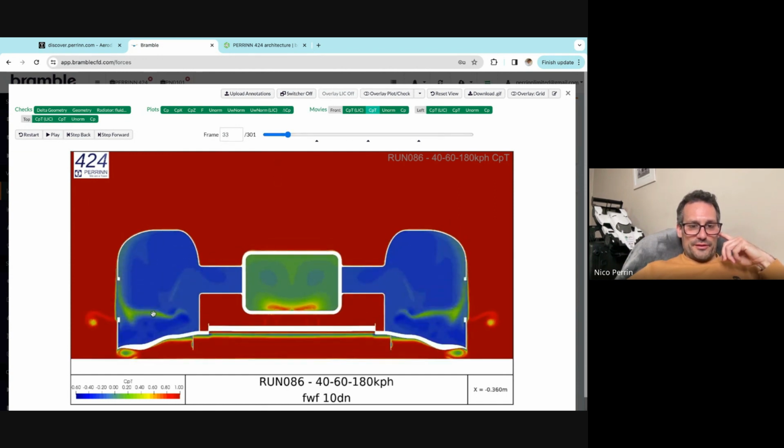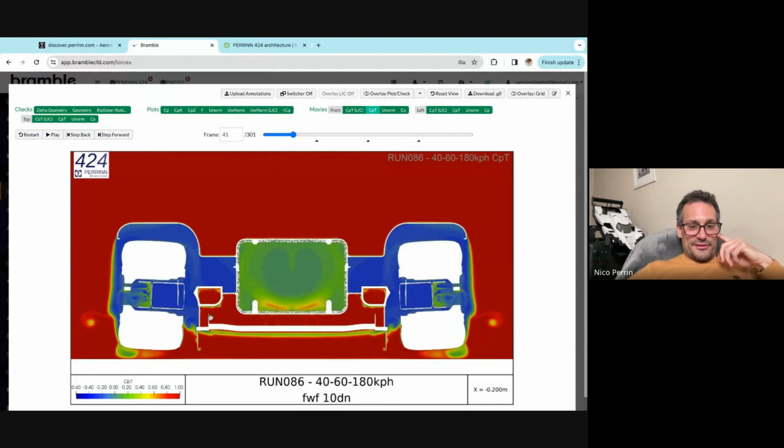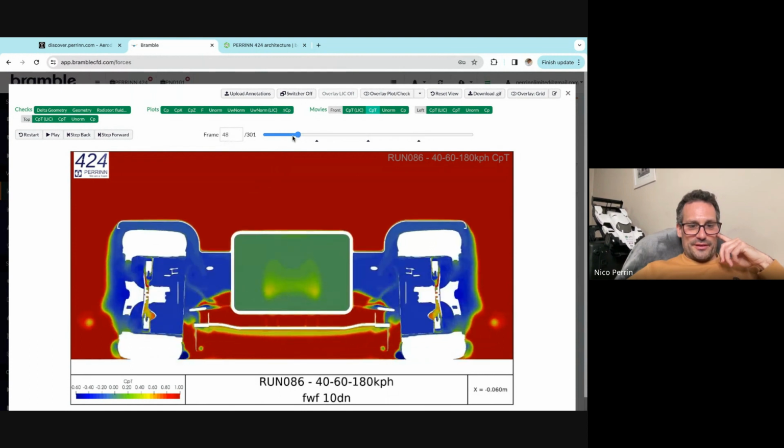In fact, inside the wheel arches, it's dead flow. We call it that because there's no velocity associated with it. Remember the story about isolating the flow from the wheel arch? On here you can still see bodywork, but as soon as we get to the suspension area, the bodywork has disappeared, the suspension legs, and the flow is free to go inside the wheel arches.